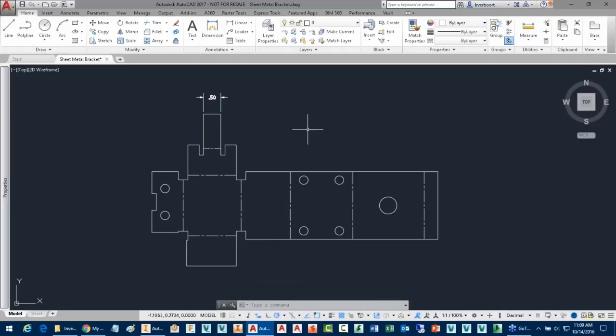So this really is just the AutoCAD environment at this point. And in fact, if I needed to, I could DXF this out from within AutoCAD. All the tools I have available to me in AutoCAD are available to this particular block, including things like explode. So if there was some reason that I needed to explode this to break the elements down into their rudimentary arcs, lines and circles, then I'm free to do that here. So the hurdle that you might have experienced in trying to get somebody the kind of information they're looking for, really, it's not a difficult task anymore.